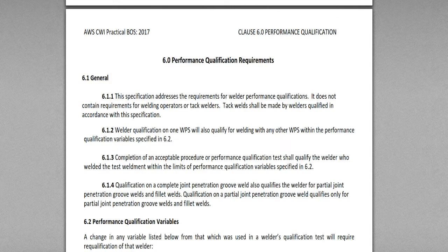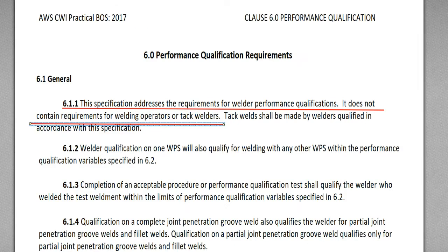6.1 General. 6.1.1 The specification addresses the requirements for welder performance qualification. It does not contain requirements for welding operators or tack welders. So this only covers welder qualification, not welding operators or tack welders. Only welders.